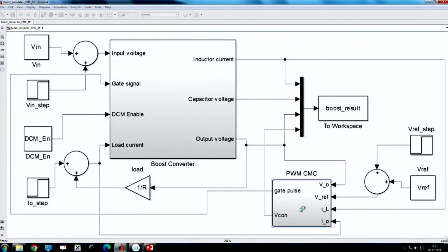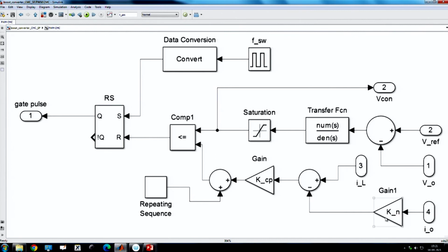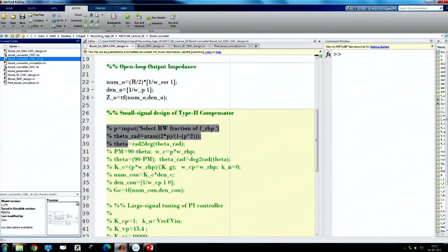voltage state, and also load information, because we have a normalized load current feed forward and inductor current, then the error current is multiplied with the state feedback gain, and in this transfer function we are using a PI controller, where we are designing the controller based on our pole placement criteria, because we are using an augmented state approach. And this ramp will come when we run it, because we have not run it. Okay, so let us go and do the simulation one by one.